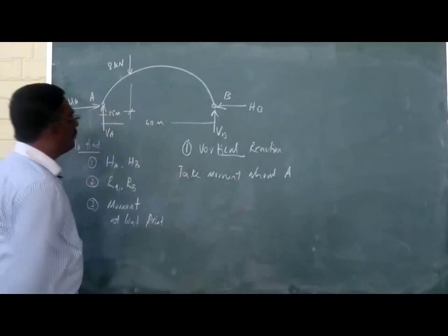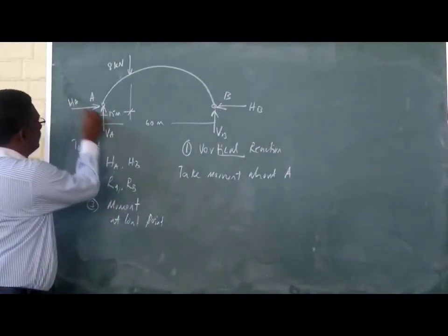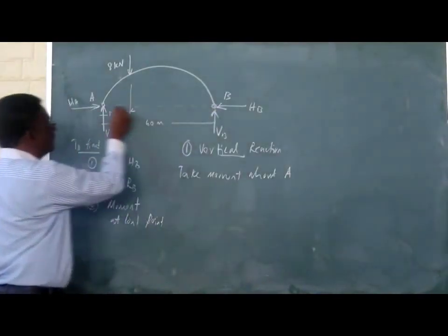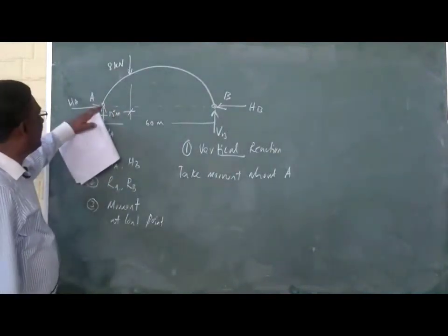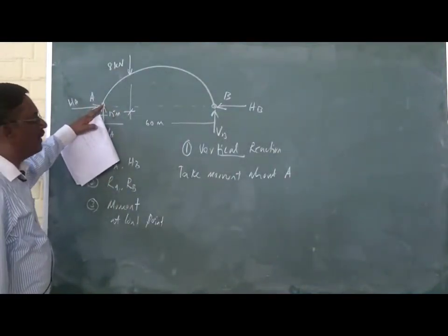Out of all these five forces, three forces, 1, 2, 3 are passing through this point, so we need not include those to take the moment.